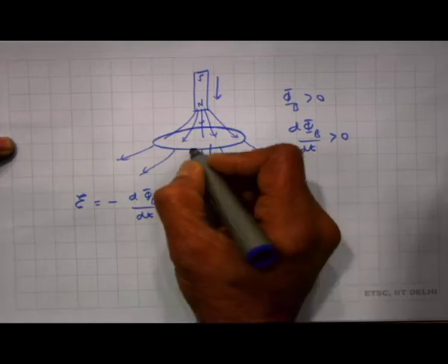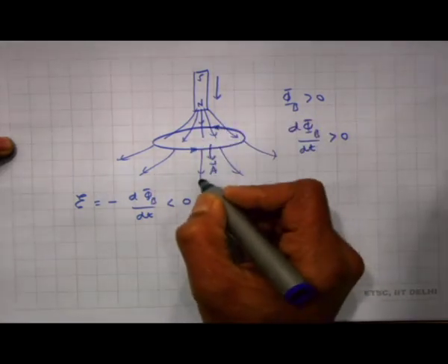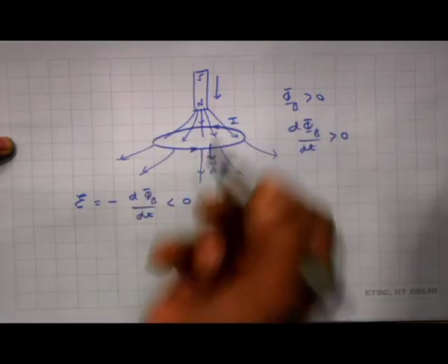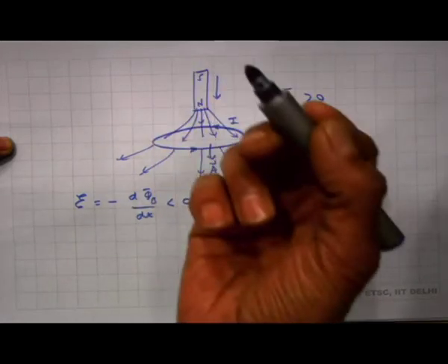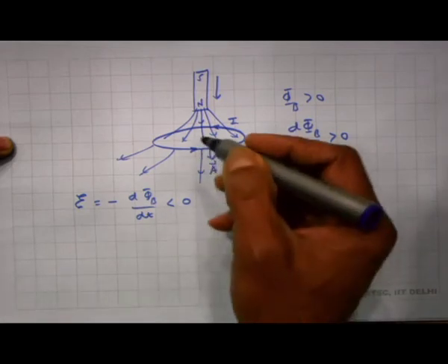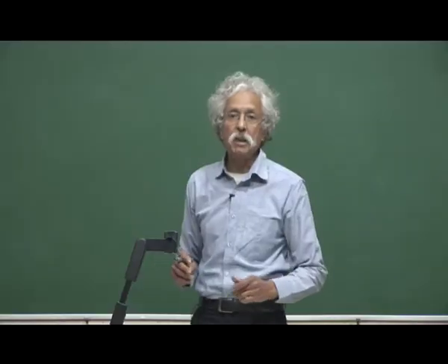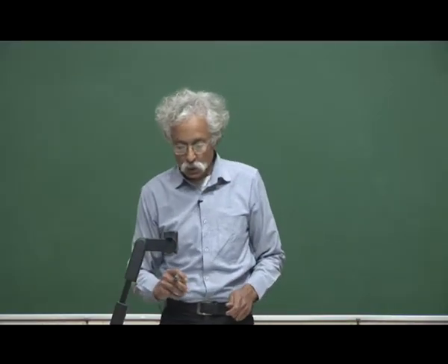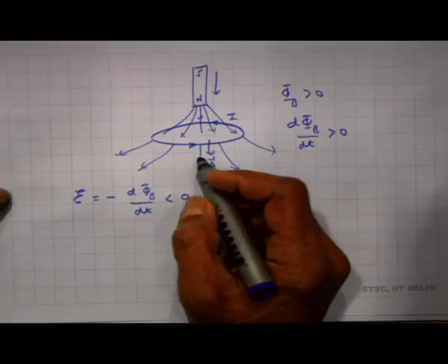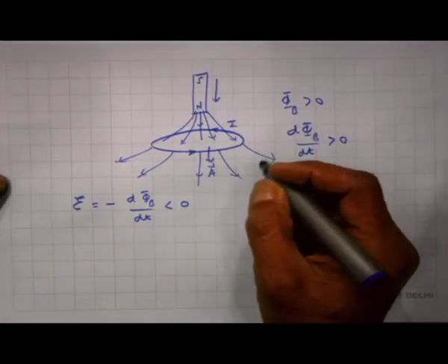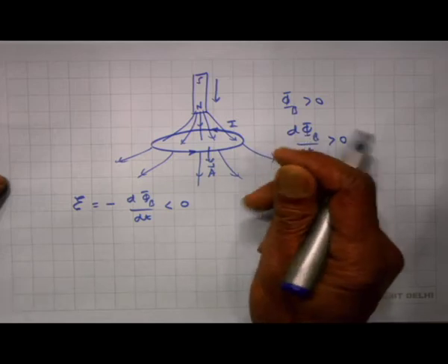So, the current that will flow in this loop will be in this direction, so that it produces the magnetic field which is upwards against the magnetic field of the magnet and tries to control the increase in magnetic flux. So, the direction of the current in this conducting loop is determined by whether the magnet is moving towards the coil, towards this loop or away from this loop.